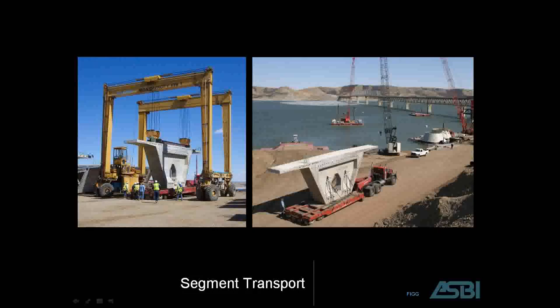So those are positioned out in the lake, and then piling are driven through the template that's in the base of that footing shell, which acts as a dual purpose, and then the reinforcement is placed in there and then cast. The segments you see here on transport is a pier segment. Like I say, it's a relatively thin segment because of the weight.